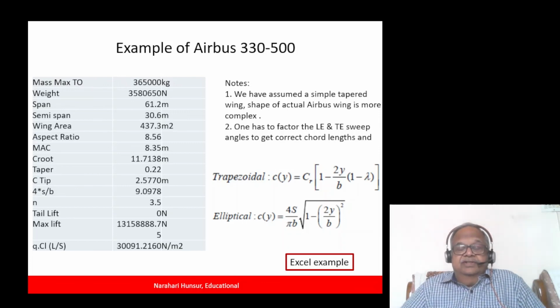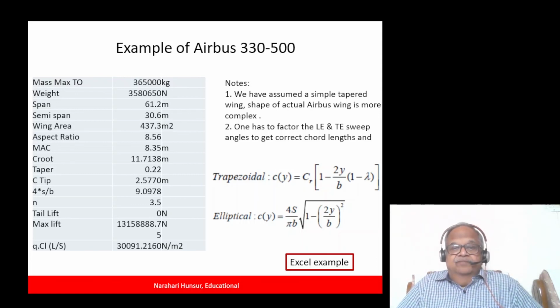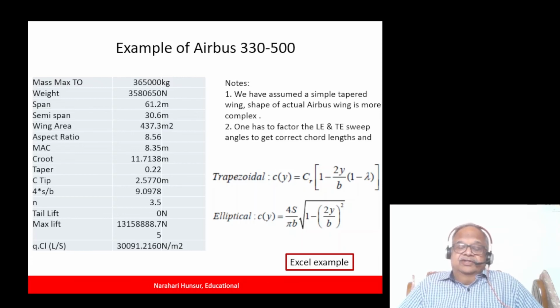Okay, so in this equation, the elliptical chord comes with 0 and goes right up to a slightly different chord than what is the actual chord. So the Schrenk's approximation is take average between these two. That is, add these two and divide by 2. That will be there, and then you have delta y. Since the first point is the tip, strip itself is in, you have to go to the next point. So elemental chord at that time, elemental area, that is delta S, and the shear force load coming on that, and then bending moment. Bending moment is that force into the distance from the root.